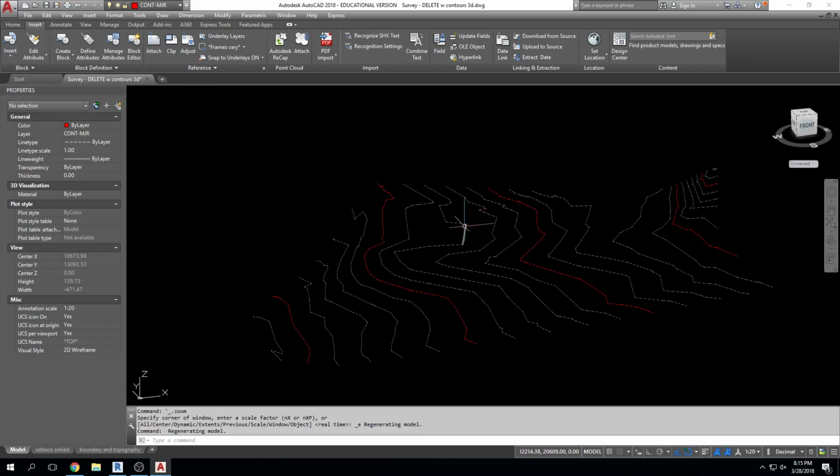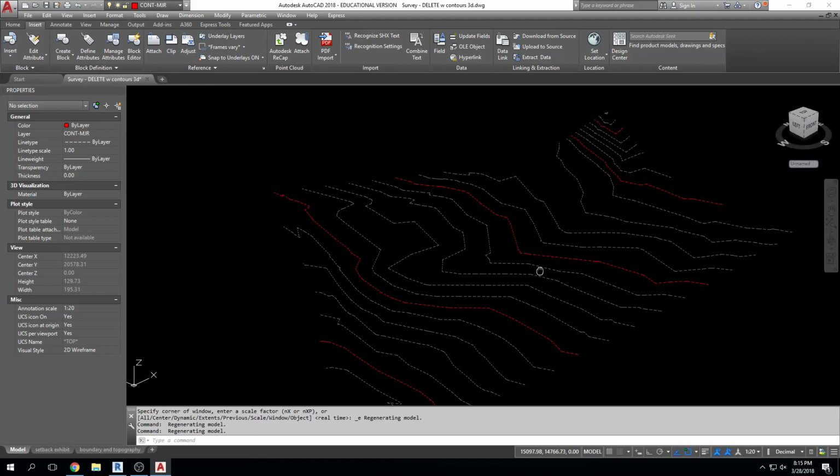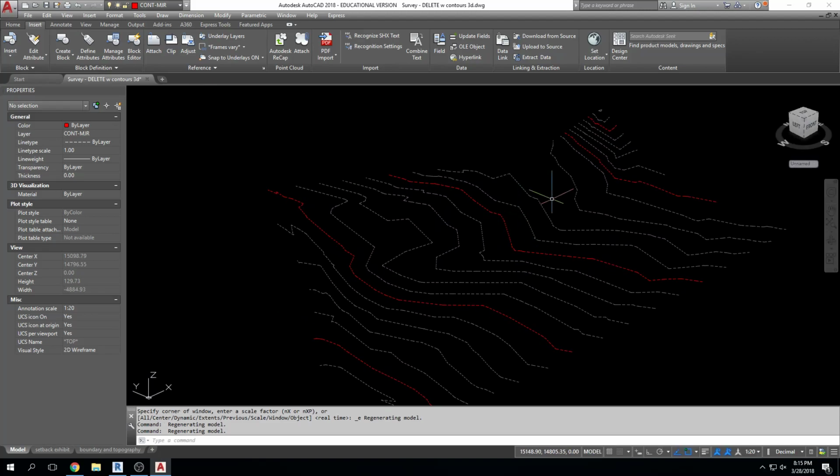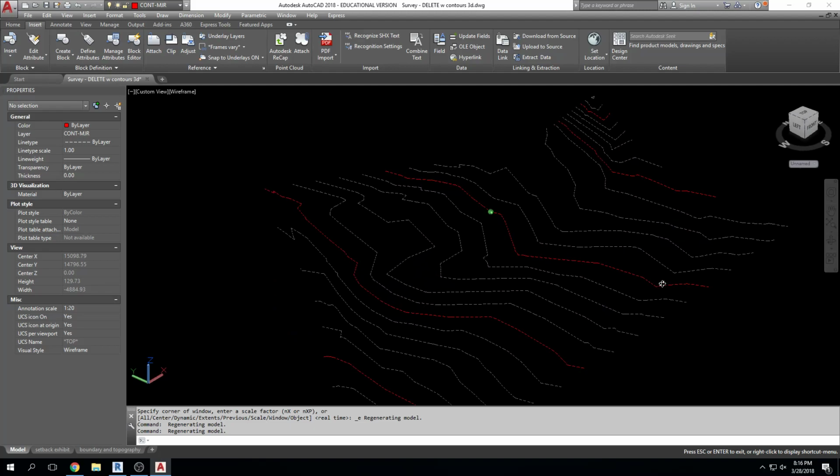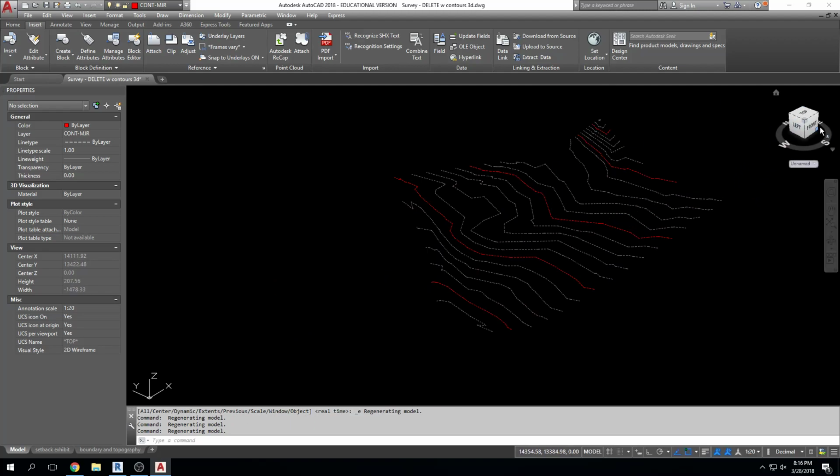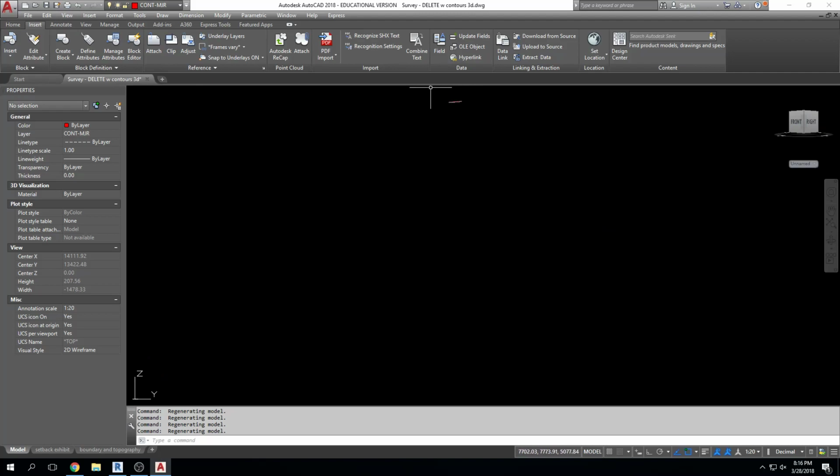And I don't think a lot of times clients really understand how important topography is to a project. How your architecture really interacts with the site is really important. But this is what the CAD file will look like. The most important things I want to point out are that it's a 3D CAD file. You get it from your civil engineer or surveyor, hopefully your engineer, so that they take responsibility for it, and that it is a 3-dimensional file. So these topos are at actual height above sea level, essentially.